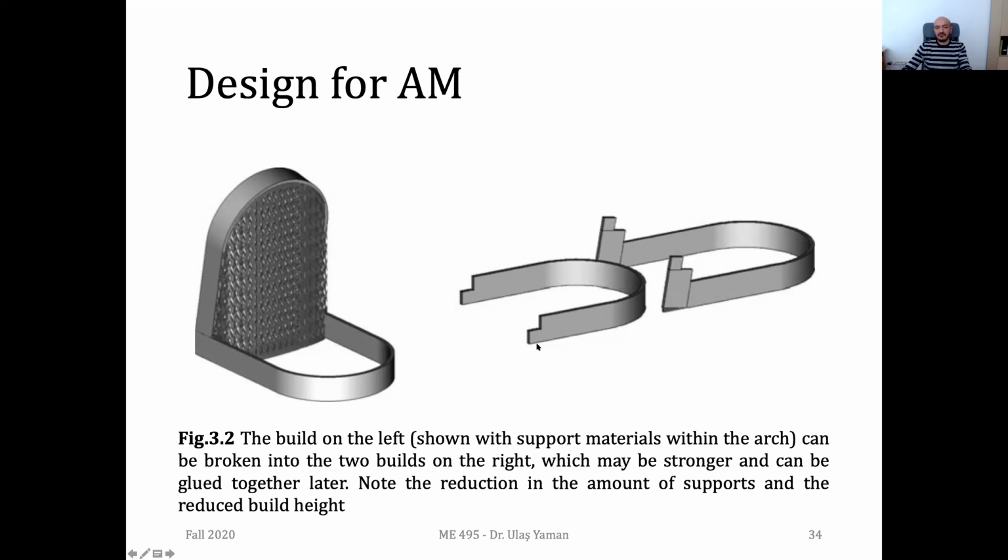And the thing is that later, after the parts are produced, we need to join them by maybe using a specific type of glue here or a specific type of maybe shrink fits. It's up to you. And again, it's better to do it with shrink fits. Otherwise, the user will spend more time on finding the appropriate adhesive and he may not be successful.